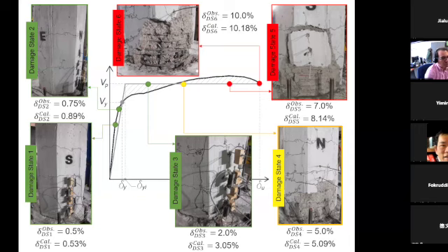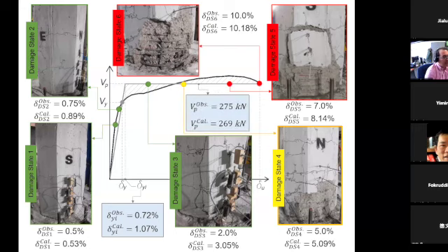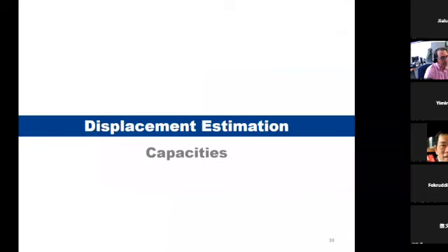We can also develop equations for something called idealized yield, or plastic forces, and find those too. Okay, we talked about damage state. We talked about how you can estimate displacement demand during the earthquake above the capacity, and at what displacement the bridge column fails.